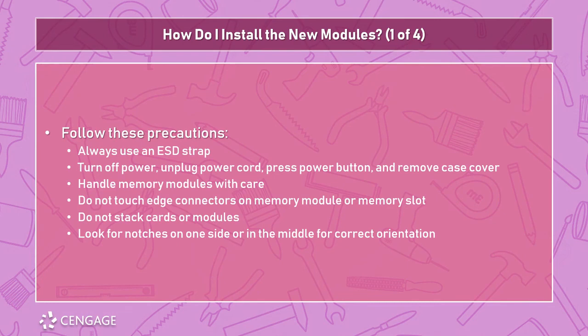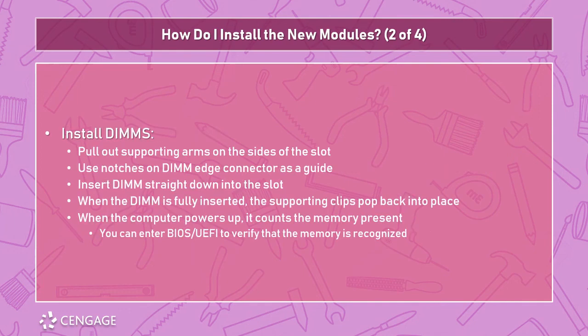Same thing we did in the teardown lab. Make sure you wear your ESD strap, full power discharge, don't handle the edge connectors, don't stack them, and make sure you're orienting them correctly using the registration notches.